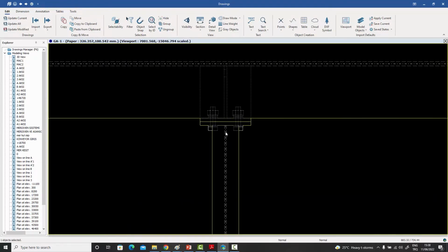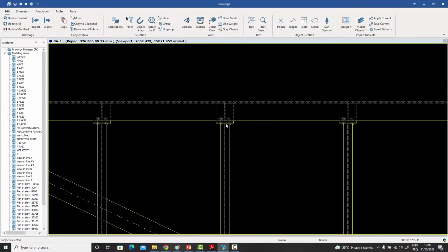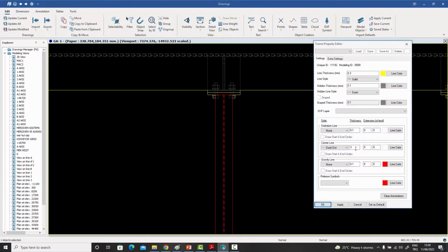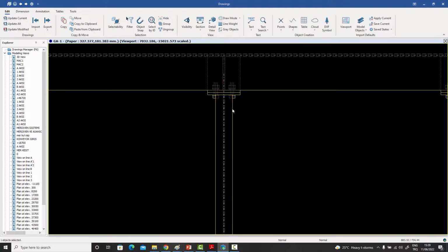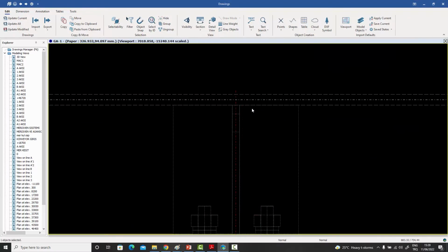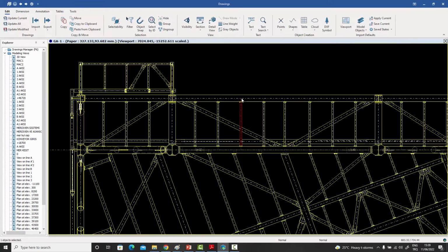It wasn't previously there. But what I don't like, for example, if I were to double click on that, I want to extend. I think this is the one. Yeah, this is the extension. This is the thickness. Actually, I did it wrong. Let me put it back at 0.1. And let's do an extension of 3 millimeters. Yes, so even 3 is not enough. So maybe I want, say, about 6 millimeters. That's probably a better number. Yeah, that looks like a reasonable number for a general.